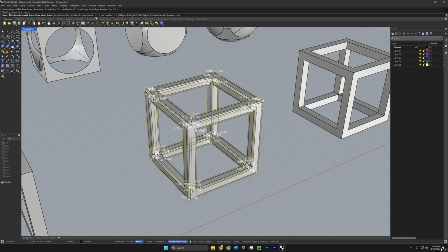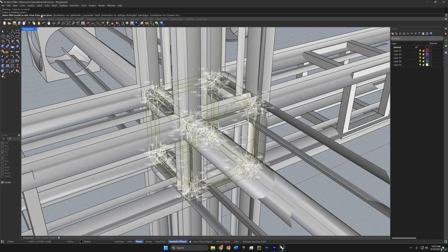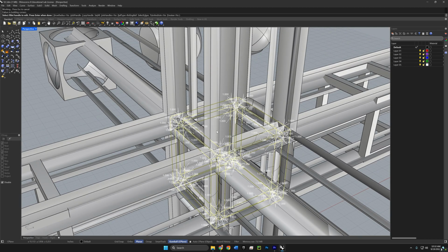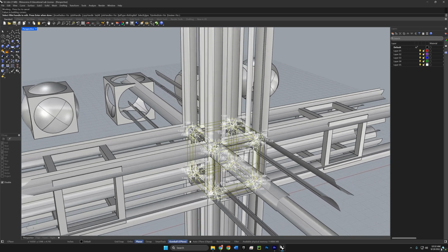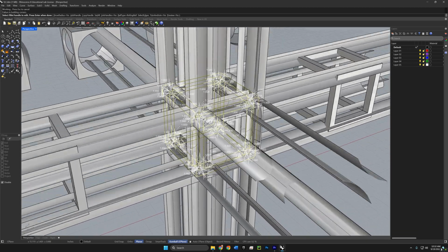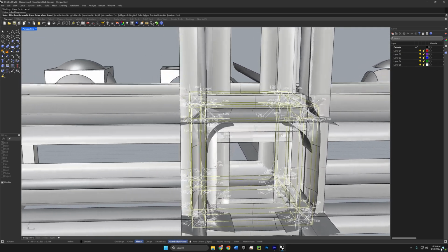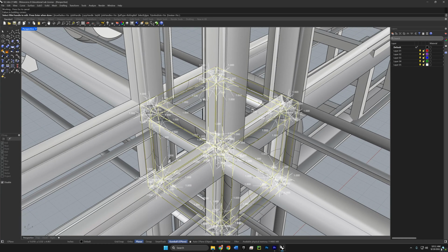And let's go ahead and set all. I want you to see what can happen if the fillet radius is too great. So with preview turned on and the fillet radius cranked up to 1, we're getting these wild results where these surfaces are extending way off of the original geometry. That's because the radius we're putting on there is so great that it's causing a lot of self-intersection problems. So we need to turn this down to be something more reasonable.